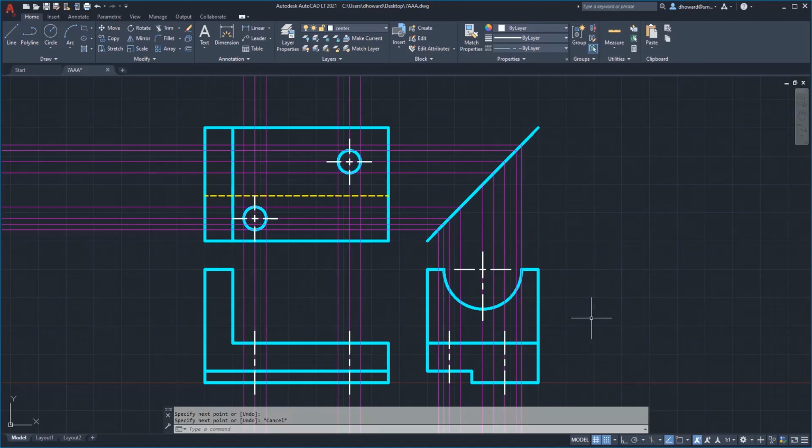That's basically how you would do it. You might be tempted to bring it out and do something like this. But the truth is that's just confusing because now you have this line running into object lines, and someone looking at this, especially if it was all printed in black and white, might see this line and wonder, is that just the object line going across? You know, what is that? So the better thing to do is to actually have a space right there like that. So the only one that's actually extending beyond the object is this line right on the bottom there.